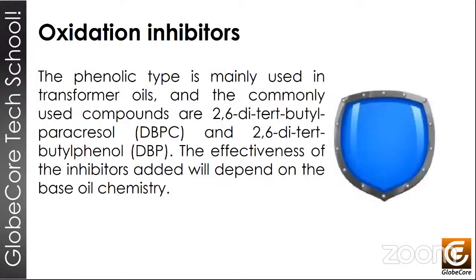So, okay, inhibitors. These are compounds that are deliberately added to certain oils to improve their oxidation resistance. And there are several types of dielectric oil, actually two types, right? So we have type 1 oil and type 2 oil. Type 2 is oil that has inhibition compounds. These compounds react with oxygen and various other elements which cause decomposition of the oil. And when the inhibitor reacts with these things instead of oil, the products of these reactions are not harmful to the dielectric oil or its performance, okay?